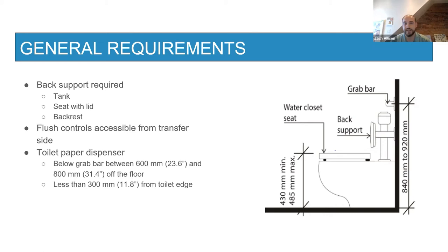So the question came up, are there options on different widths for backrests? It's pretty well standardized at this point where there's really only the one width available, but you do see different depths, or at least you should, because the spud, the inlet connection, for a top-spud toilet on a floor-mounted model versus a wall-mounted model is a different depth from the wall.